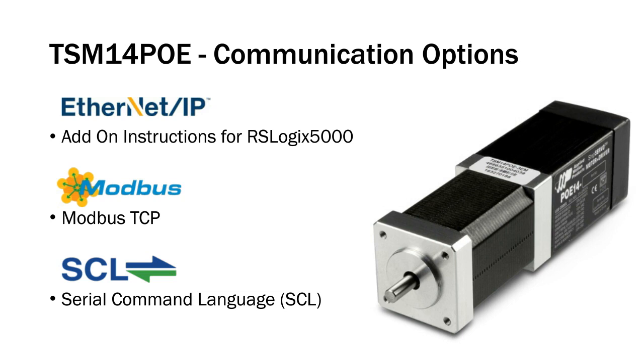might use. We also offer add-on instructions for RSLogix 5000. So if you have a Rockwell PLC and you want to incorporate one of these devices into, say, a CompactLogix or ControlLogix project, it's very easy to do with those add-on instructions. We also support Modbus, which covers pretty much every other PLC out there and a lot of HMIs as well. And then we offer